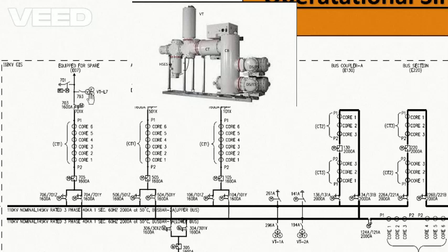These three-phase VTs will take an input of 132 kV or 110 kV and step down the voltage to typically measurable voltages of 100 volts. Then these are fed to control and protection and metering. This is a separate field and we will discuss it in detail in some few videos, hopefully.